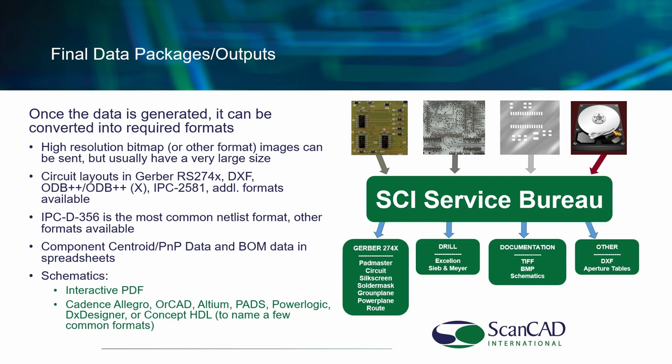Once we have all of the data for the circuit board generated, we'll convert it into your required formats. If desired, we can provide you with the high-resolution bitmap images that are captured in the process. Although we start our data generation with Gerber RS-274X, we're able to export TXF, ODB++, IPC2581, and additional formats.